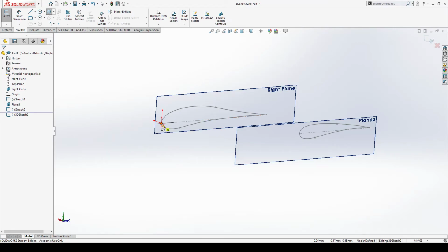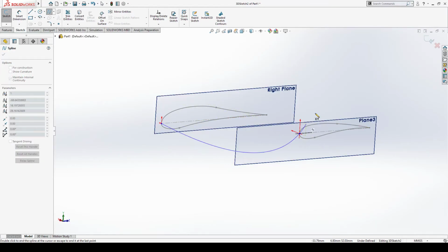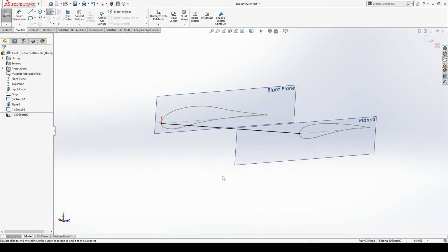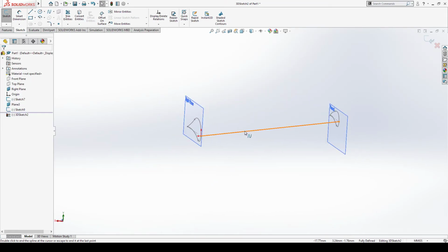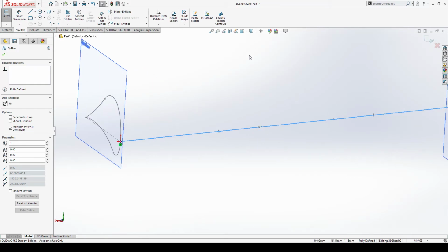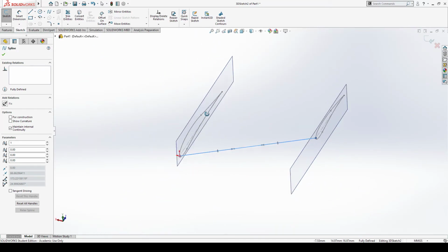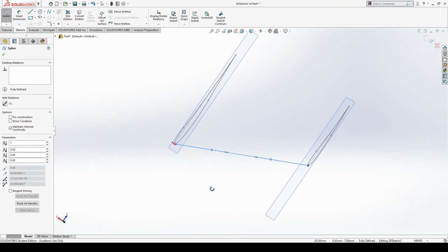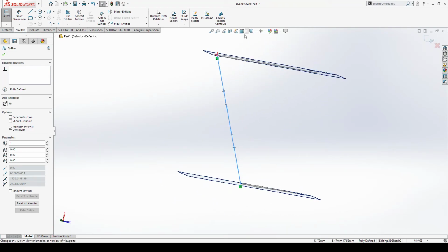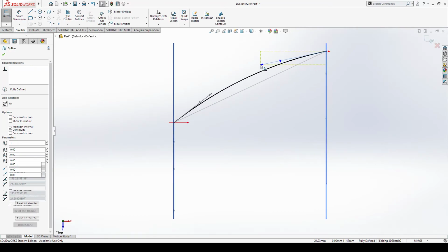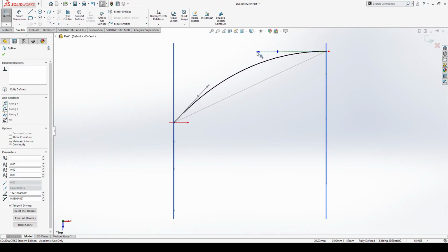I'm going to connect the leading edge of the first aerofoil to the leading edge of the second. Okay, just the 2 points. And we can use the control handles on these to define the shape of this leading edge. So this is how it looked before with the normal loft, just a straight linear interpolation between the two. But with this, now we can make it into a more interesting curved shape. Again, we can set the angles for these handles down here. So I'm going to make it sort of like a recurve on the front.